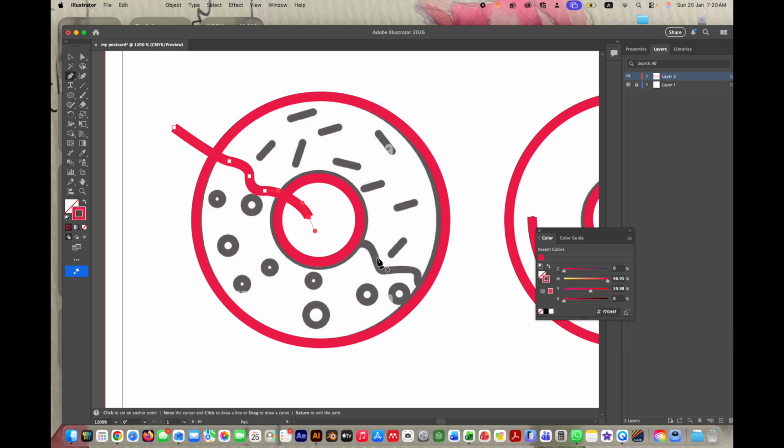Again, go to the pen tool. Click from the outside, click one time and then release your finger. Click on the second part, click and release. This is the second place, click and release, click, release and hold. Click, hold your finger and then drag, so you get this area. And then press V to release from the pen tool.